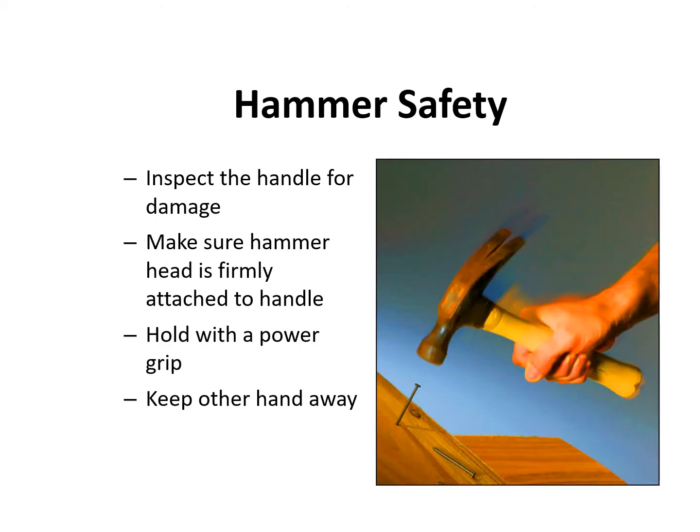When using a hammer, inspect the handle for any signs of cracking, splits, or other deformities. Make sure the hammer head is firmly attached to the handle. Hold the hammer with a power grip, which includes all your fingers wrapped around the handle. Keep your offhand away from the hammer's strike zone.